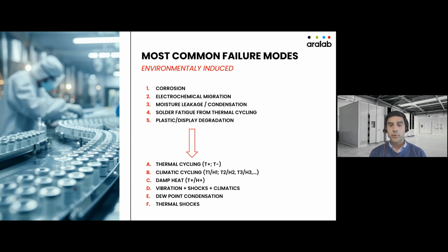Can you imagine the probes on the nose of an airplane that are flying at -50 for 8 hours or 10 hours or 12 hours? And then if they have to do an emergency landing in, I don't know, Saudi Arabia or a very, very hot climate, in a matter of minutes, they may have to go from -50 to +80. Okay, so this is very common, and this is one of the main uses of climatic chambers.